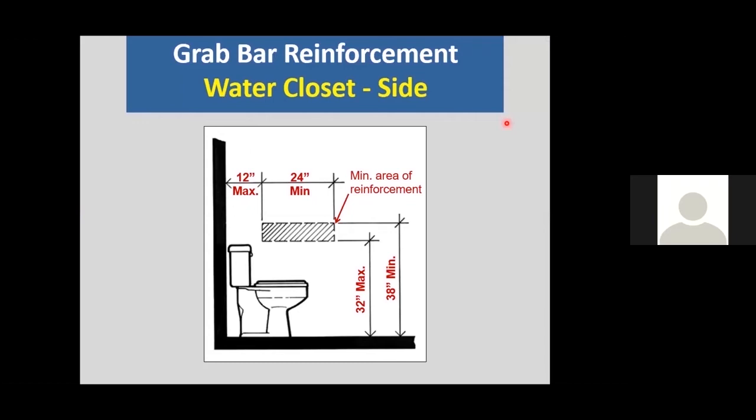Yes. The question is, does the requirement to provide reinforcement in the walls of the bathroom for handrails include reinforcements that are lower and would allow for attaching a shower or bath seat? That's a very good question. There is one condition for showers only where reinforcing for a shower seat would be required.